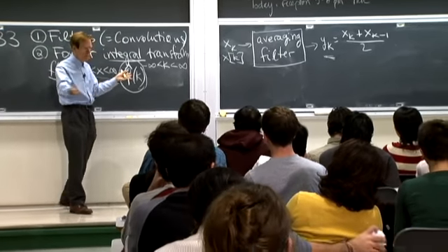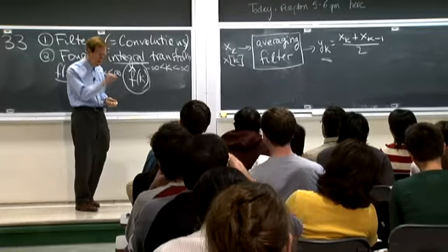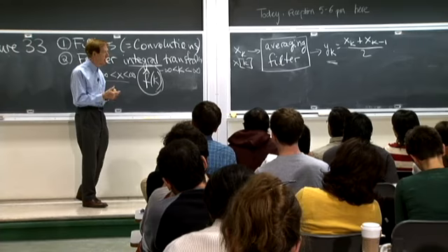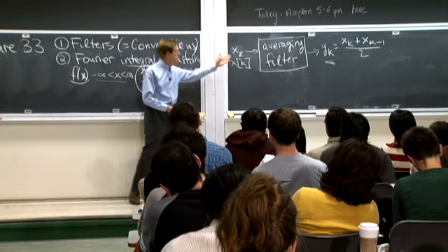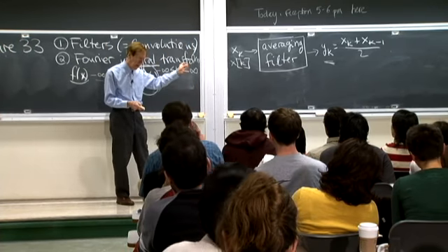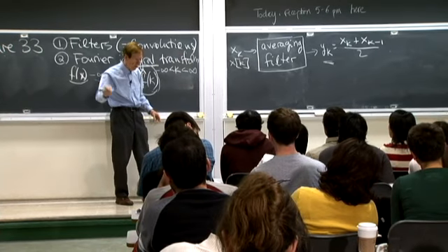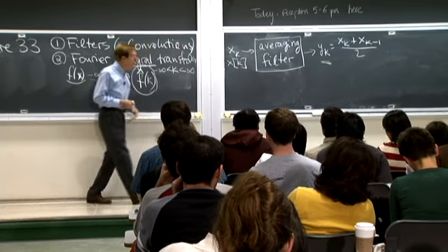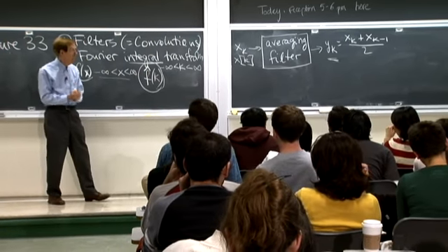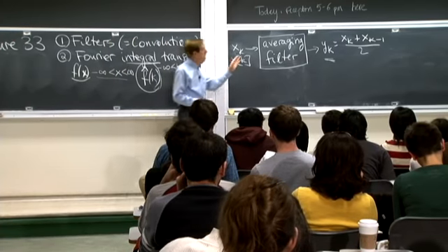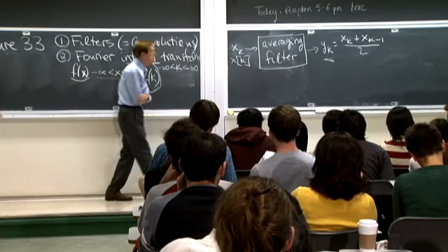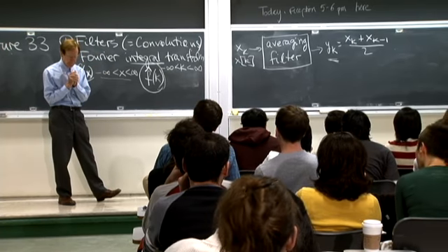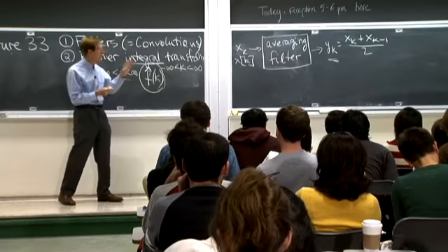But if it's a CD or something and you're sampling it thousands and thousands of times, then the input signal is so long and you're not really caring about the very start and the very end. It's simpler to just pretend that you've got numbers for all k. Okay. Then let's see what kind of a filter this is. What does it do to the signal?